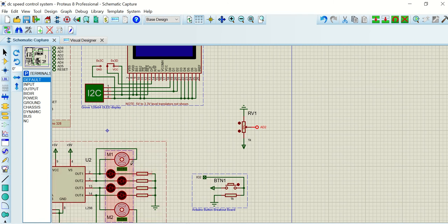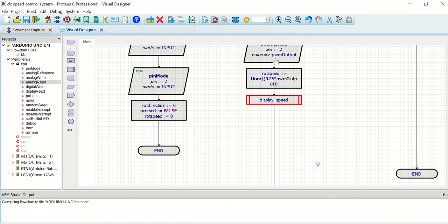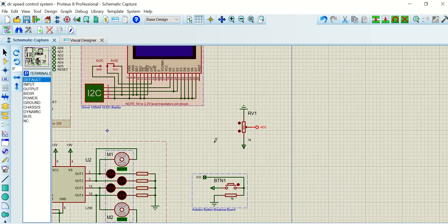And along with that, for controlling this motor, this analog read operation for our PWM duty cycle determination, varying the duty cycle values, is already set up as you have done in loop. Analog read operation is already done, but you need to activate this button as well.